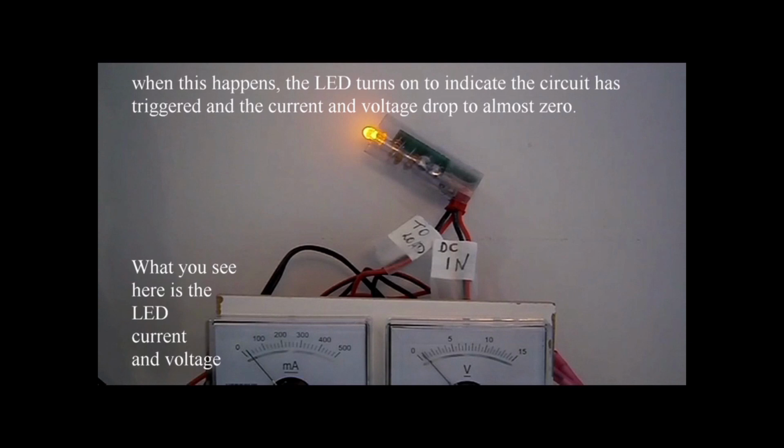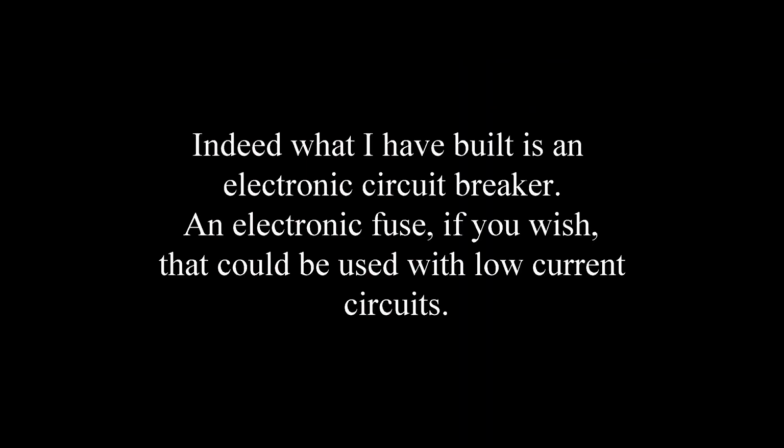When this happens, the LED turns on, indicating the circuit has triggered, and the current and voltage drop to almost zero. Indeed, what I have built is an electronic circuit breaker, an electronic fuse, if you wish, that could be used with low current circuits.